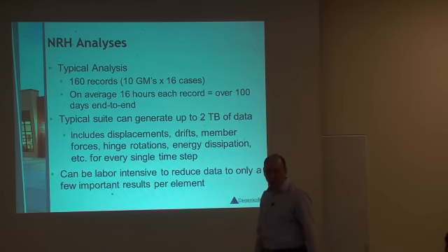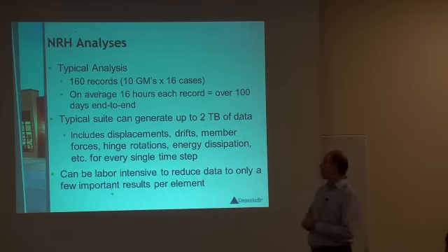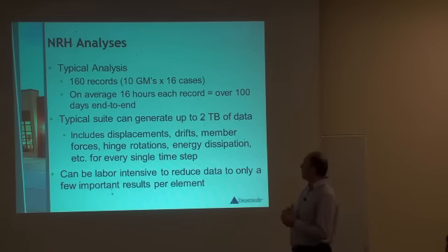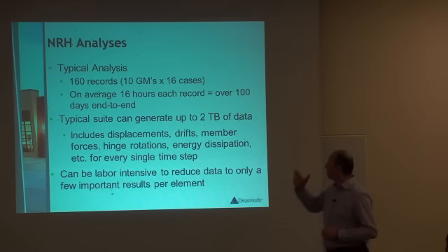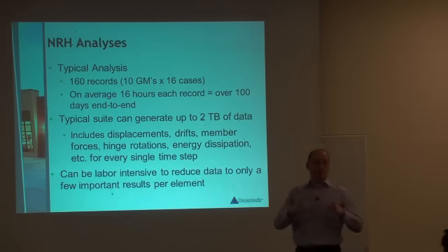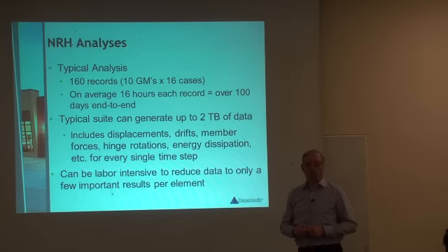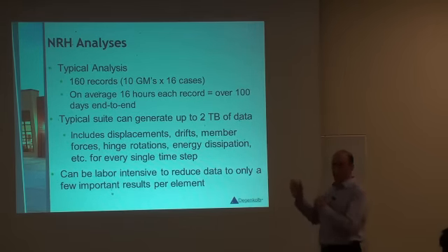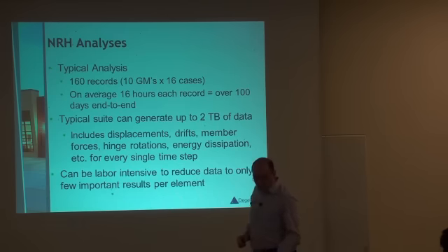So back to response history analysis. Some of the challenges of doing response history analysis for an actual project is that you're sometimes looking at many runs. So this last hospital I showed you, every time we modified something in the model, we had to do 160 different response history analyses. 160, why? I mean, we only used 10 ground motions, not 7, by the way. But it'll come in a second. There's many combinations that we need to look at.